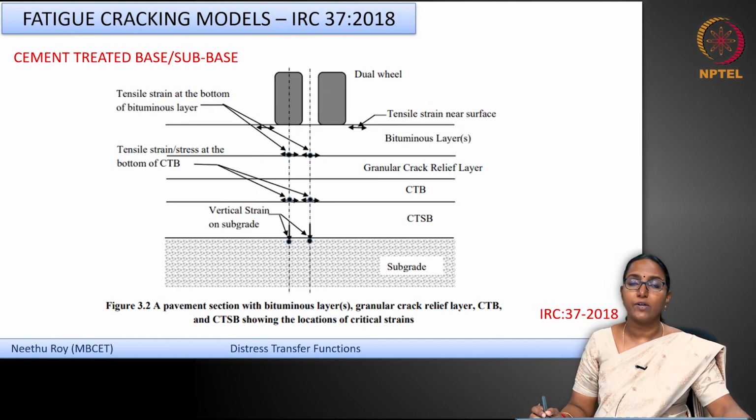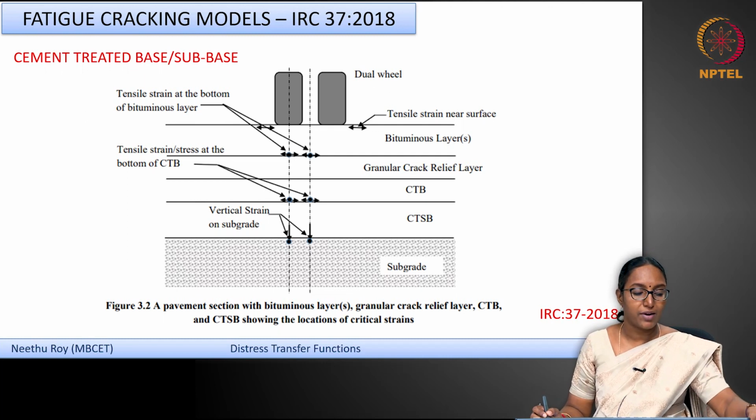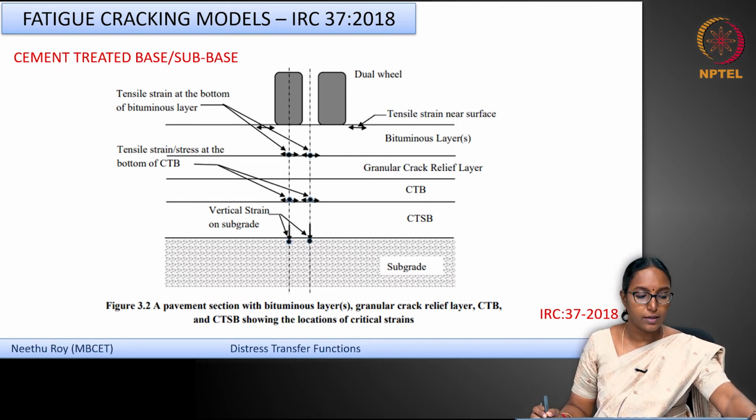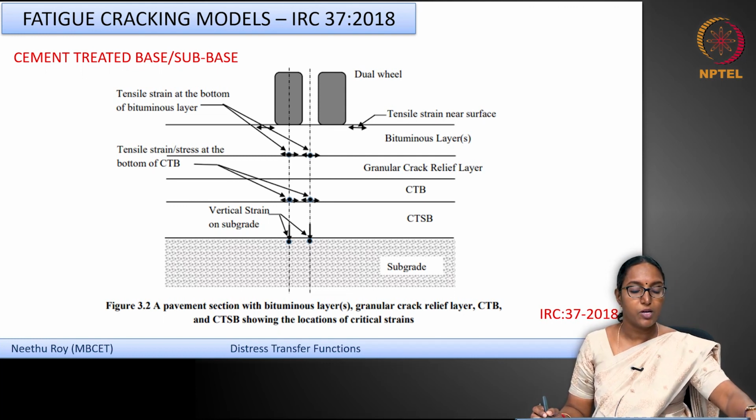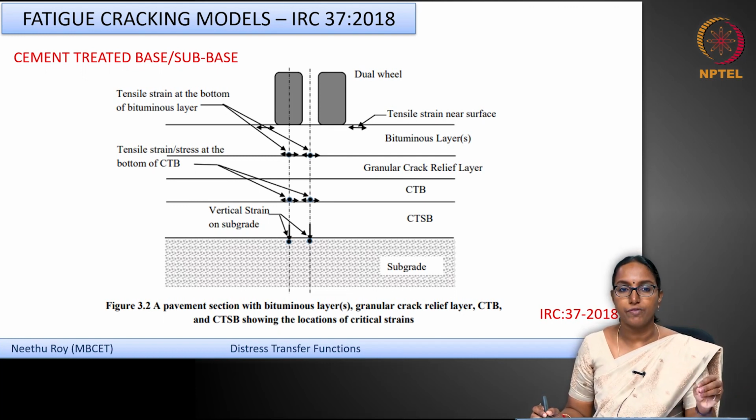Now, as far as IRC fatigue cracking equations are considered, we are not using this damage approach or the Miner's approach as such, because you are just comparing the number of repetitions to failure as one, which you get from the one distress equation. So, for n number of design years, you find out whether the design is safe or not.